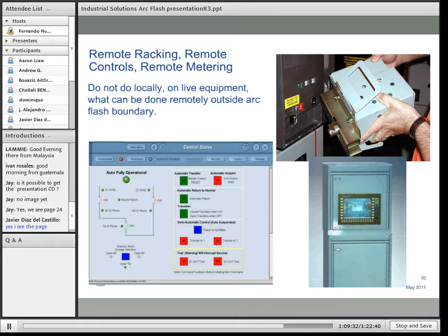And so there might be a false indication of an arc flash when it was just normal arcing that was safe. And also sometimes the doors don't seal tightly and there's light coming in from outside. So you have to be a little bit more careful with the light sensing.